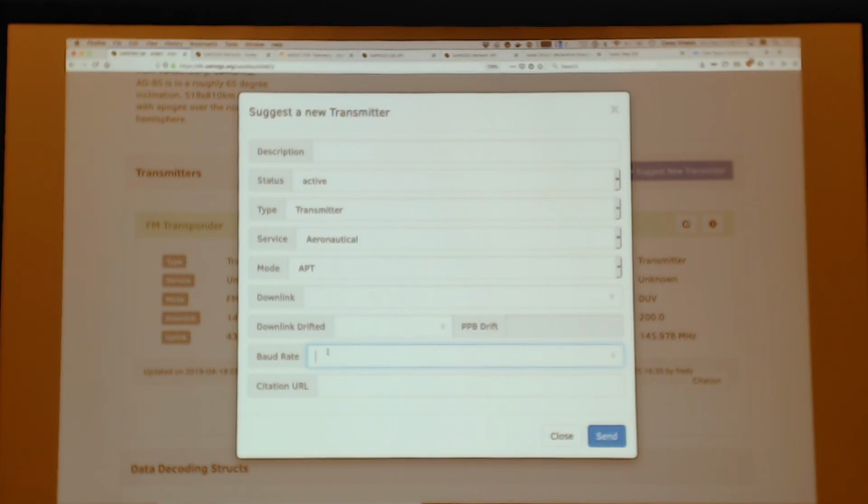The idea is that with that receiver you can plug in a different baud rate, and the GNU Radio scripts are going to adapt to that new baud rate. We've tested it on satellites that are up there. So if there's a new one and it's a non-standard baud rate, we've not tested it at those baud rates, right? So, all right. If you do select transponder, do we come up with the extra fields?